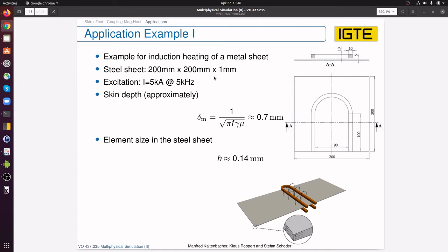And then it also depends on the kind of resonator circuit you're using, and typically you have certain types, or, I don't know, 3 types of frequency generators available, and you need to design your capacitor bank to this particular application, so that your resonant circuit with the inductor, so this has to be included into the design of the whole setup, acts at a certain frequency.